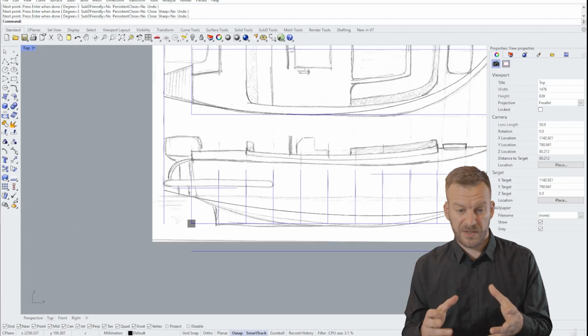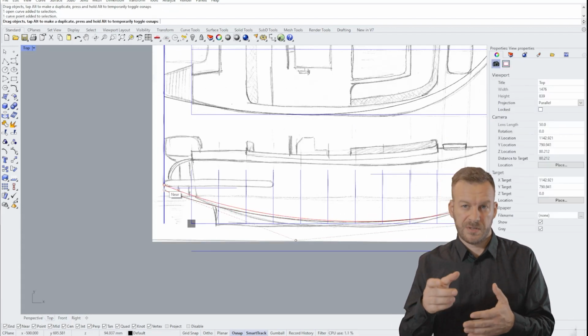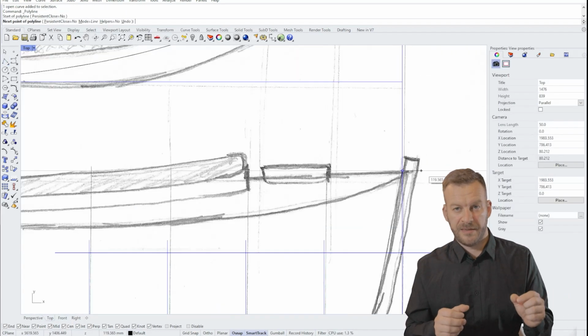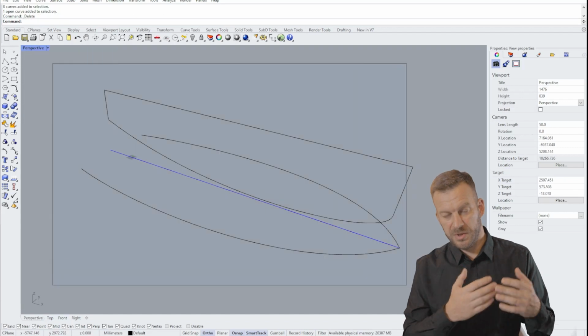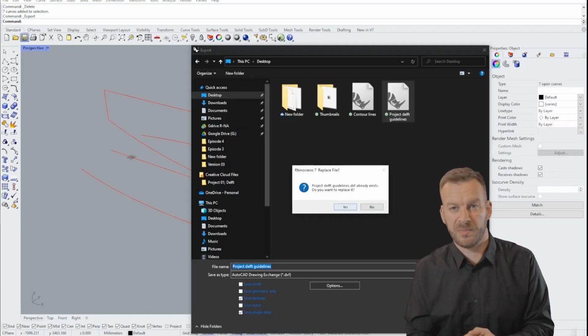It's a very early stage. The sketch is more of a guidance than something that needs to be followed blindly. When the shear lines are finished, I will start drawing the center line. I will start with the bow stem first, and then I will create the keel shape. After that I will create the deck line, and then I'm going to remove the back image and rotate the projections and prepare them to export in a DXF file.